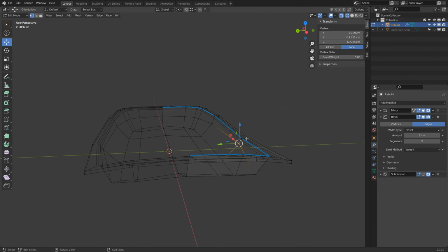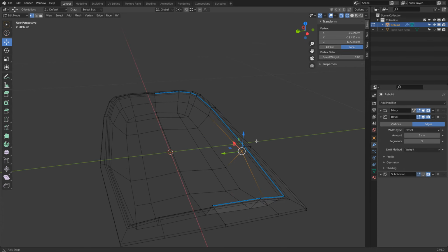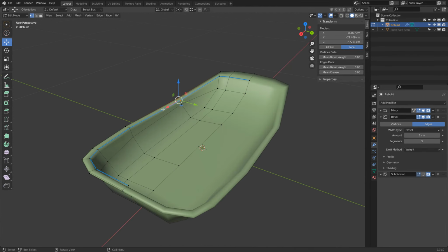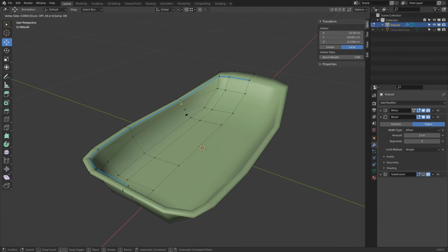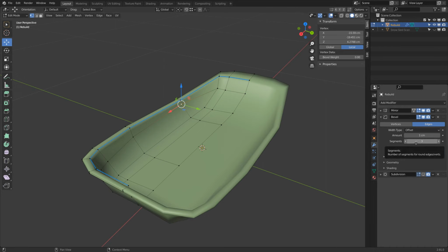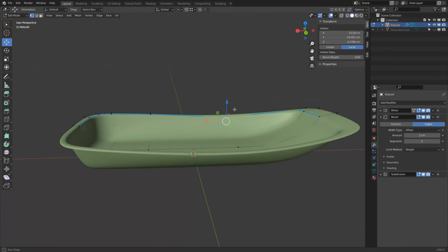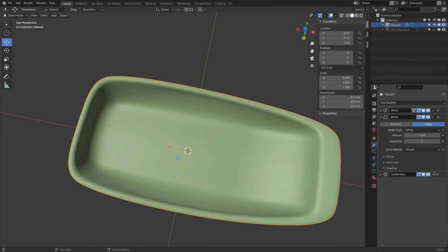Okay, I also notice here this is very tight. This is at a nice line, but you can see because we pushed this one down, I might have to select this point and later GG slide this down a little bit. I'm not sure, so I will leave it there for the moment. But with this edge beveled with a segment of 3, 1 centimeter, let's turn this on. And yeah, there's a nice rounding.